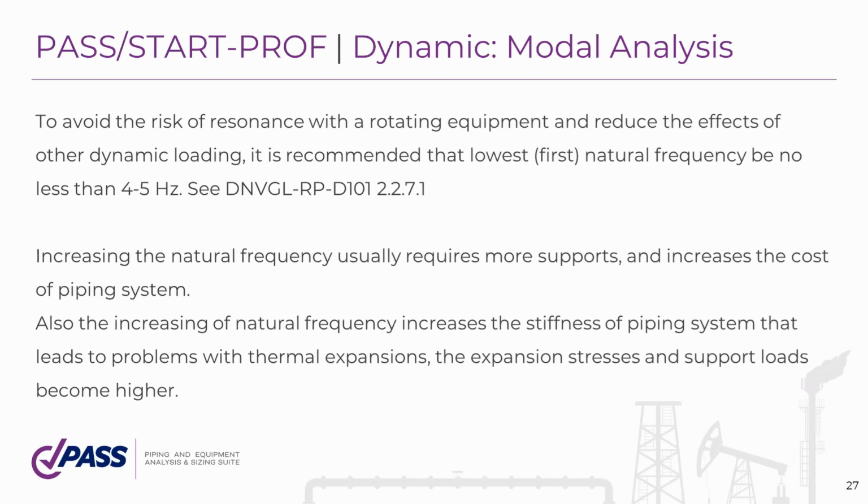Some companies have internal requirements that natural frequencies should not be lower than 4 or maybe 5 Hertz. And this recommendation is also added to the DNV-GL recommended practices: the lowest natural frequency should not be lower than 4 or 5 Hertz.